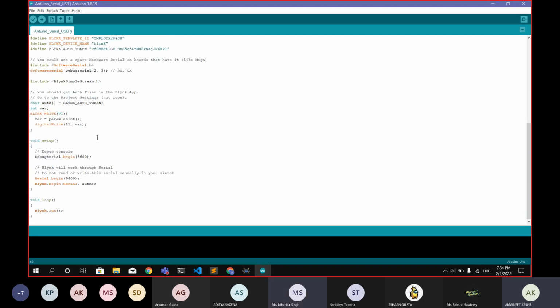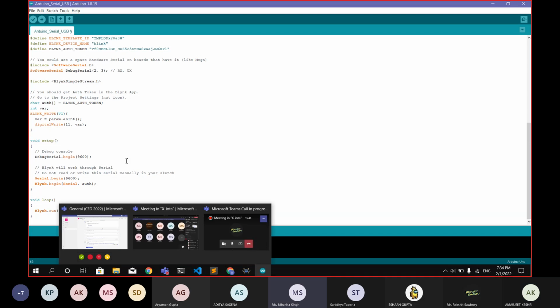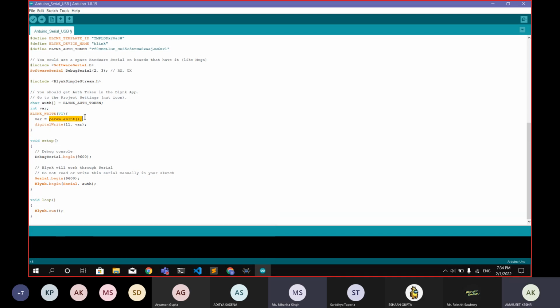Okay, Sir, what is the meaning of param.asInt in the variable? This is written as param. Param is the input from the v1. V1 is giving us the input from the Blynk application or Blynk interface, okay, the web interface or the Android interface, whatever you will be using. So we will be getting the V1 from the pin number V1. V1 is the virtual pin, okay. So we will be getting some values, okay, param.